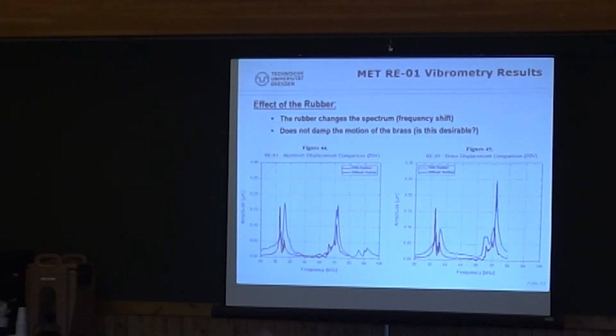the bracket, right? This is actually what I've also observed, and it's not in this presentation, but if I look at the displacement of the brass mass, it's actually distorted when there's no rubber. And when there's a rubber, it's a smooth sine. Exactly what I expect. That's why in aerospace, if you're going to put anything together and you have to go through thousands of cycles, by cycle fatigue, you're never going to connect to something solid. You have to address the contact problem.